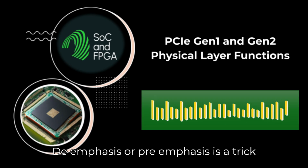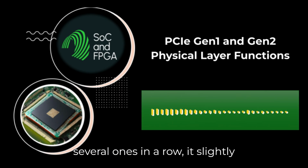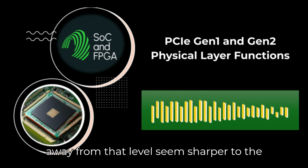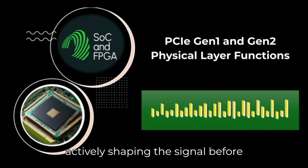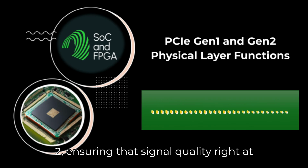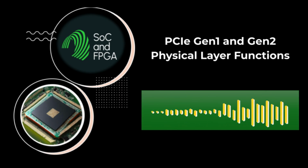De-emphasis, or pre-emphasis, is a trick the transmitter uses. How does it work? If it's sending a run of identical bits, say several ones in a row, it slightly reduces the voltage level after the first bit. This makes the eventual transition away from that level seem sharper to the receiver, helping counteract the channel's filtering effect. So it's actively shaping the signal before sending it. Yes. It's a basic form of equalization present even in Gen 1, Gen 2, ensuring that signal quality right at the start is a core PHY task before any digital magic happens. Okay, shaping the signal. Let's peek inside the PHY now.